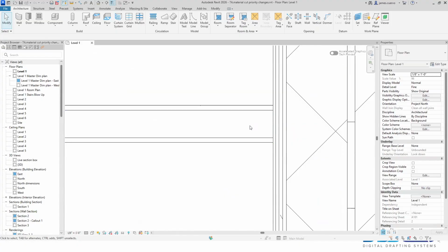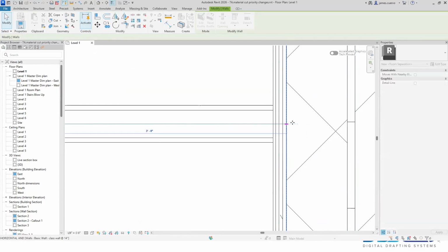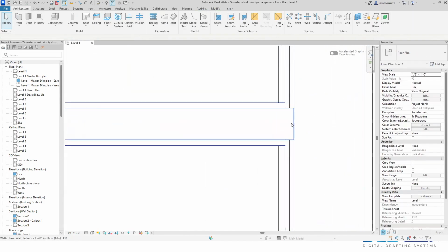So this particular wall is actually not cutting all the way to the core. Let's go ahead and make sure that it does that by pulling the point or the grip and pushing it where it is. Now you'll notice that what? It's actually now folding my chipboard, right, into the wall, so it actually is continuous, but this core does not merge with this core.